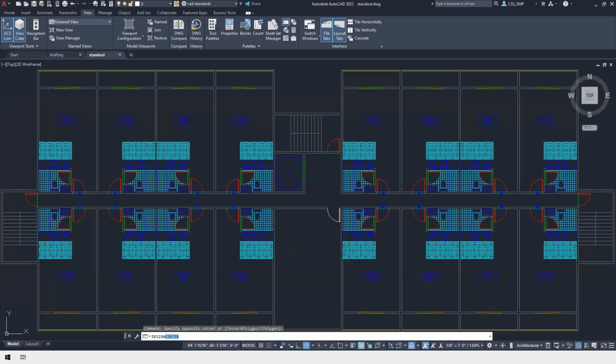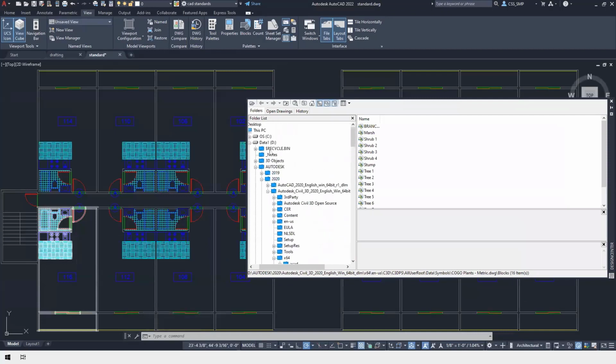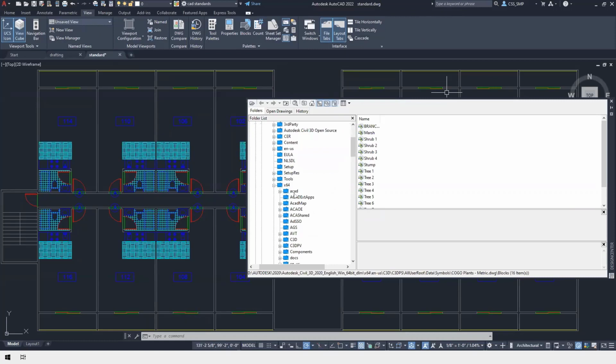We've created new layers in our current drawing. Those layers are correct. You've got your stage 2 layers or stage 1 layers or whatever it may be. You could actually come in here, open up your DWS file and open the DWS in here, open your drawing that has those additional layers in the Design Center and drag those additional layers into the DWS file, save the DWS file, and those additional layers will be in the DWS file for when you're checking your drawing going forth. I'd agree. I think that's the best way forward.